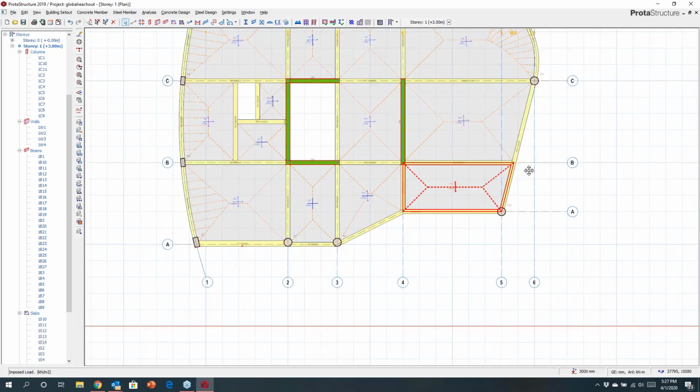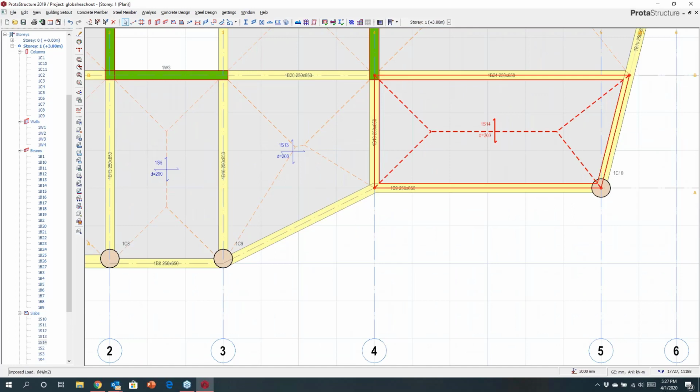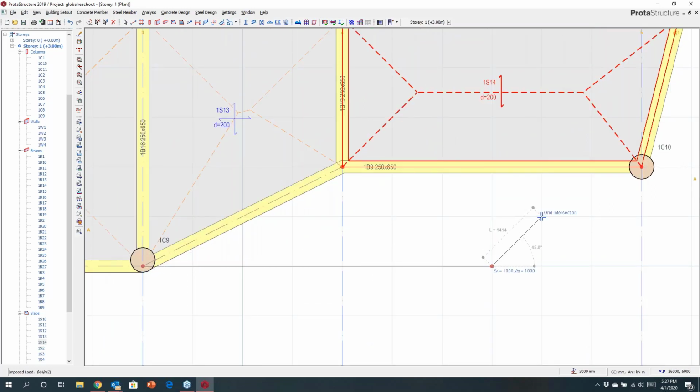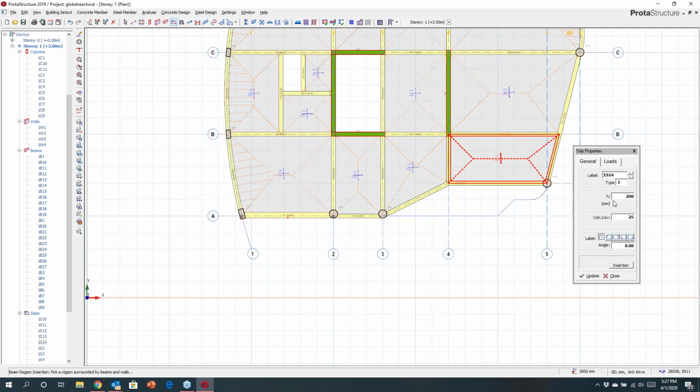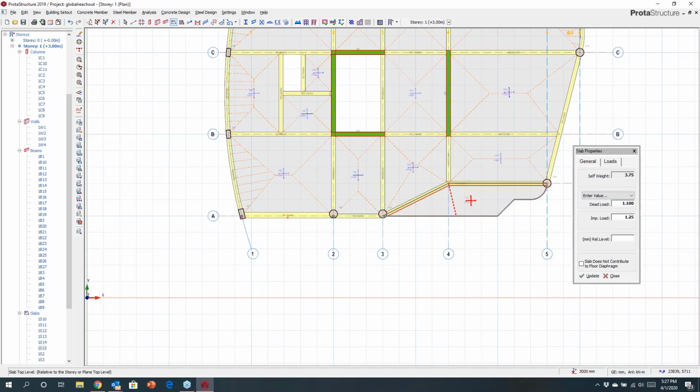Now, if I've got unusual geometry, we can also make use of what we call sketch lines. You can use these to help you sketch out a profile. So if I had maybe the side of the building, I've got a funny slab, and I can use sketch lines just to help me sketch this profile, and then we can use this to help to define that element. So I might want to put in an edge slab there. We can key in the thickness of this. Maybe I want to drop it, maybe 100. And then I can use that boundary just to help me create that slab.